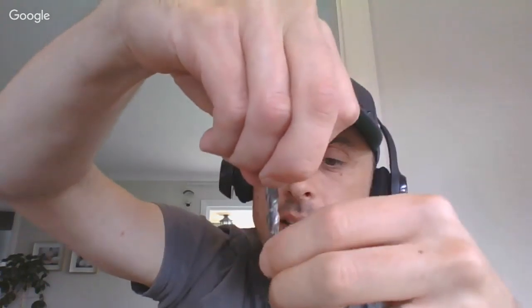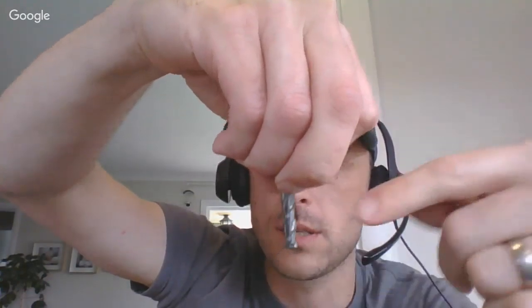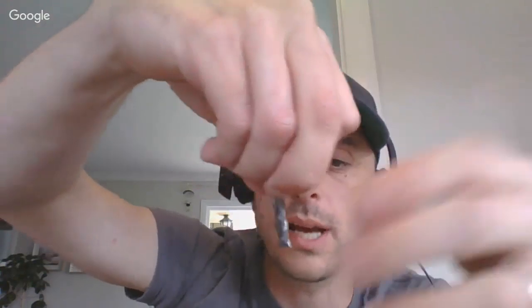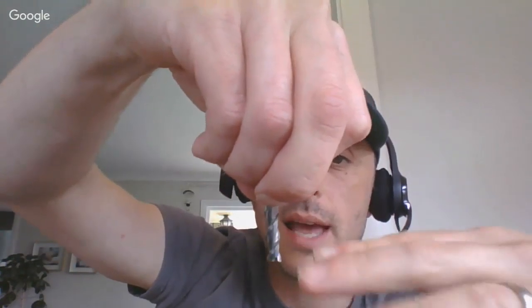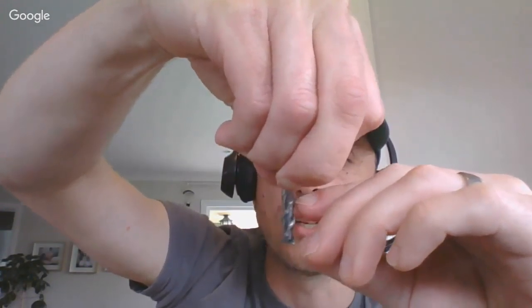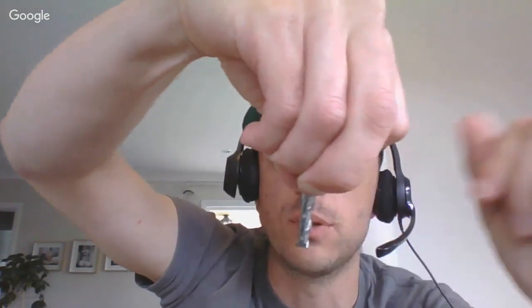In a smaller machine, or especially a desktop machine, just purely due to their size. I mean, the Vertigo is a pretty rigid machine for its size, but it's still not a rigid machine compared to a big cast iron milling machine. You can have an issue that loading and deflection is actually pulling the bottom of the cutter away from the wall, so you can actually start to end up with tapered walls. So you really have to listen to the cut and hear how it's sounding. But generally, when it starts to go wrong, you can hear it. You can hear a pretty significant change.